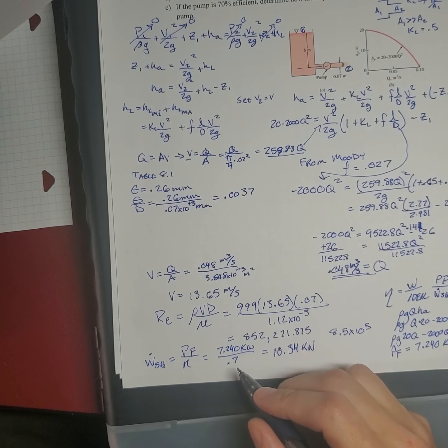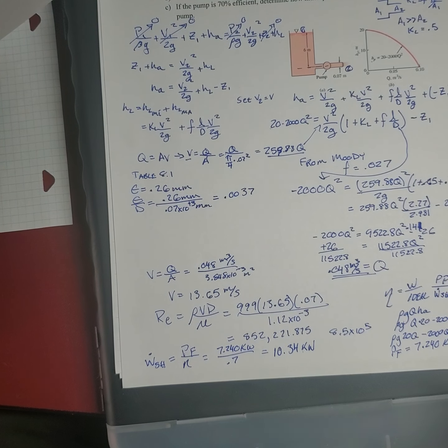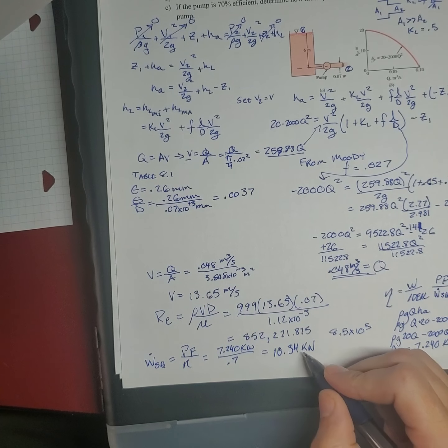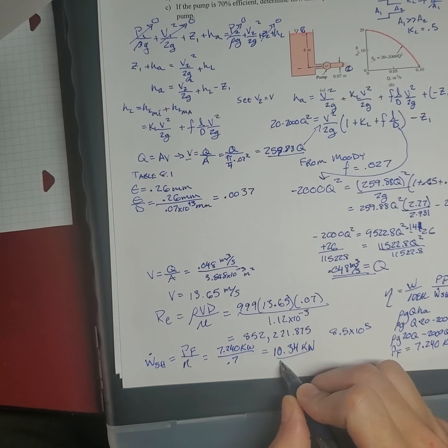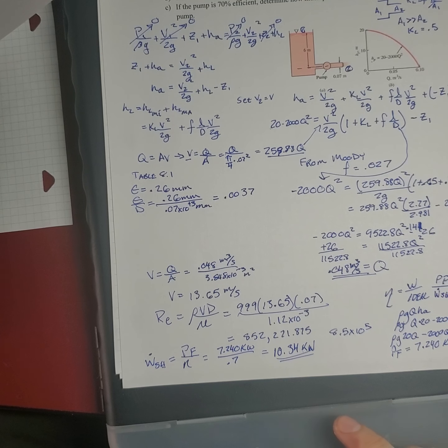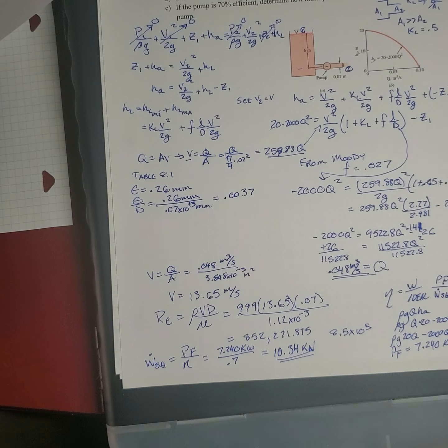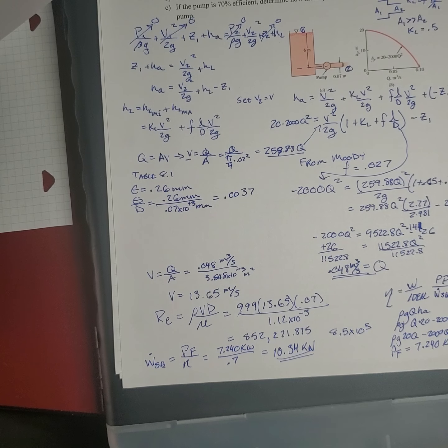which means that you are going to have an increased amount of power that you had to put in. If this was a perfect pump, an ideal pump with 100% efficiency, this would be a 1, and you would put the same amount in that you got out. So just a little double check yourself intuitively. You put in more than you got out, and that's due to a 70% efficiency. So even if you forget the order, you'll still be able to get the answer just by logic.